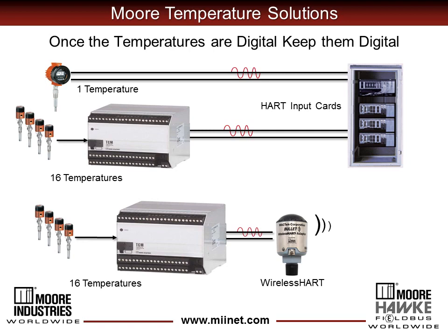If you put a temperature transmitter or a remote I/O near your sensor, these devices digitize your temperature measurement. If you then decide to send the signal back to the controller data acquisition system via 4 to 20 milliamps, you end up creating 2 more errors. There is a digital to analog error creating the 4 to 20 milliamp signal.